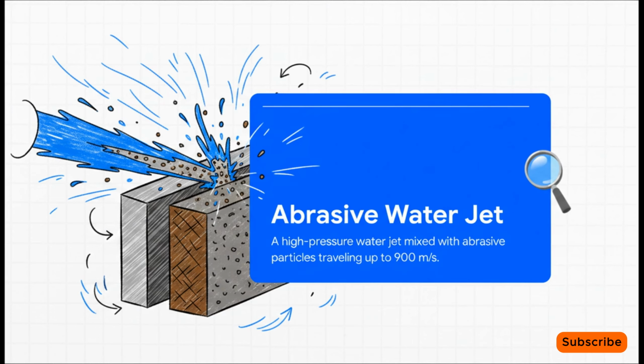Abrasive jet machining, or AJM, uses high-velocity gas and abrasives for delicate surface cleaning and deburring. Water jet machining, WJM, uses pure, highly pressurized water to cut softer things like rubber, foam, or even food. But when you combine them into abrasive water jet machining, or AWJM, you get an absolute monster.